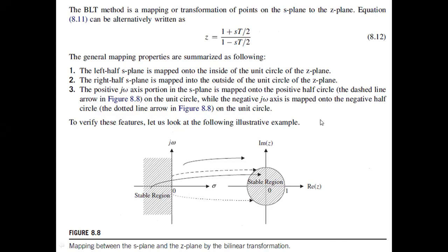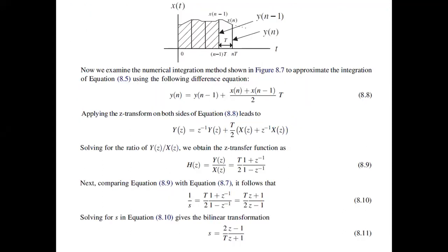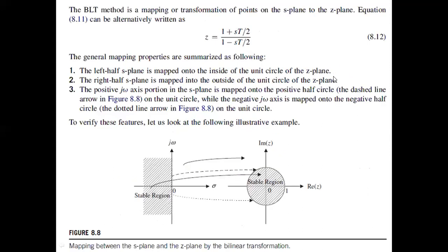As I said, the derivation of the bilinear transformation is important. The mapping from S plane to Z plane, the stability analysis and the frequency mapping are also equally important examination questions. So let us be curious. Which is the thing that we are trying to map? This thing. We are trying to do the stability analysis of this particular mapping function. Instead of having it in terms of s, we have it in terms of z here.